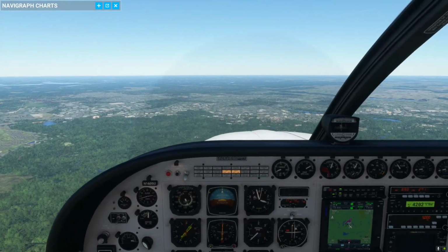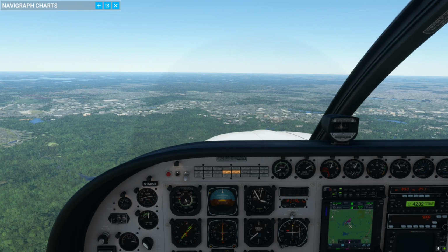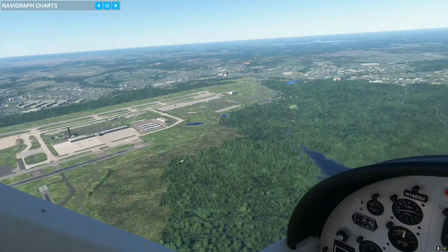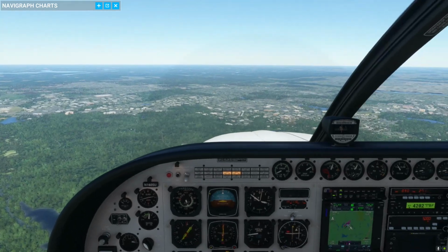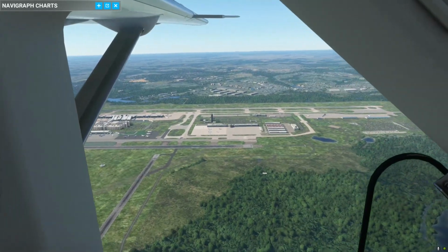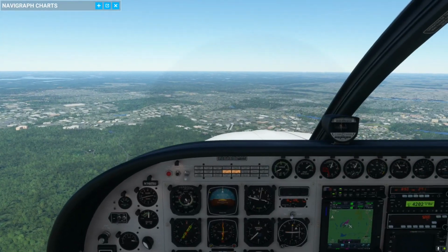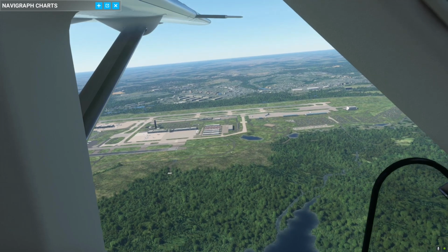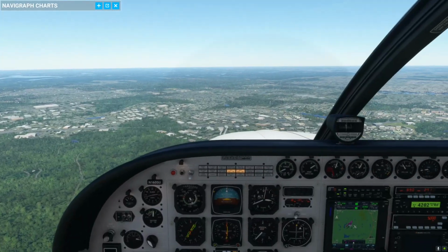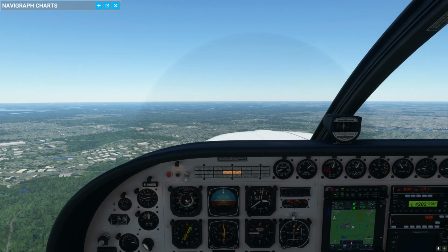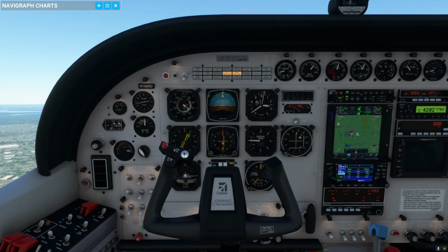That is the right airport. But now look at the direction indicator. See why I bugged the runway heading? Makes it easy to fly the downwind. I know all I've got to do is keep that at the bottom. And I'm flying the perfect downwind, while I'm trying to lose a crap ton of altitude. I'm going to go ahead and add another notch of flaps. Landing lights are on. RPM's full, high idle, fuel condition.